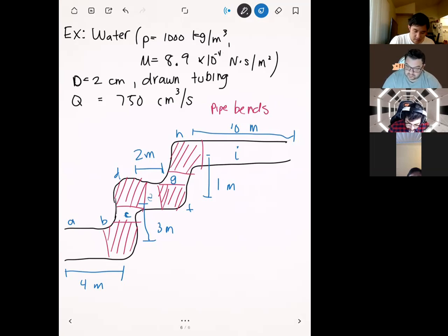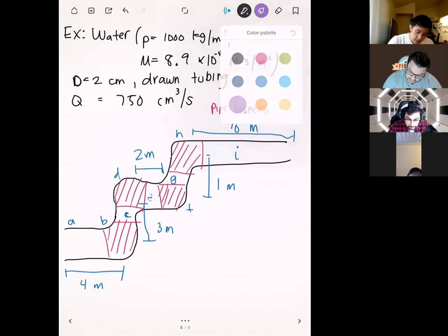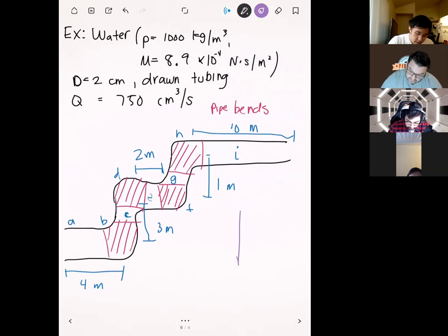In addition, we have gravity. This is going to be a pipe that travels vertically up, and so gravity is going to go down like this. In between our inlet here, so we'll call this point 1, and we'll call the outlet point 2, we have some height difference that we're going to need to account for in our Bernoulli equation. And one other piece of information that we're going to need as we look up the loss coefficients is that these elbows here are threaded 90-degree elbows.